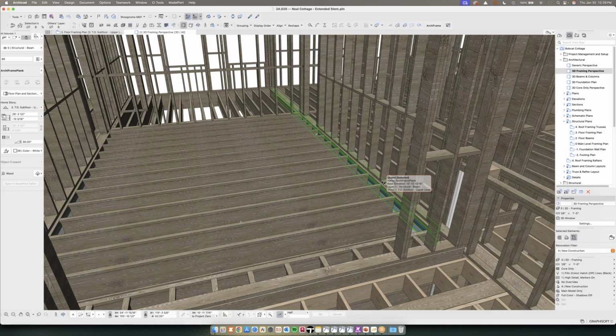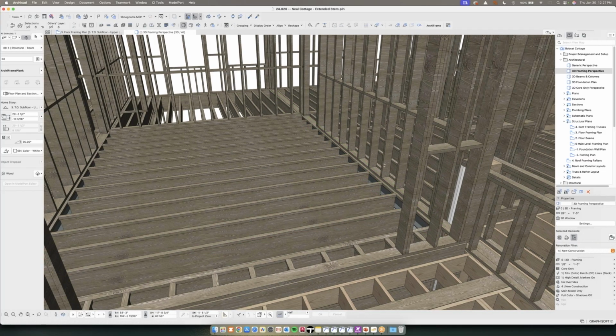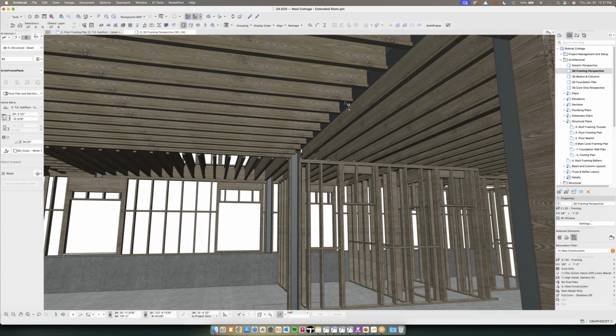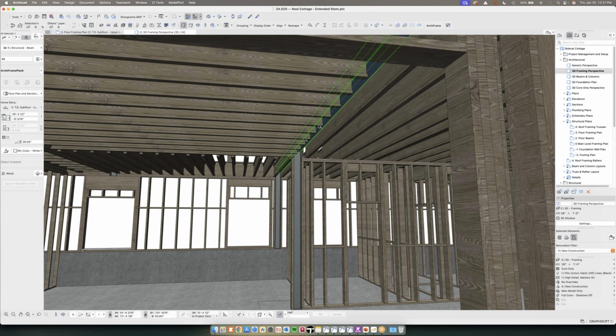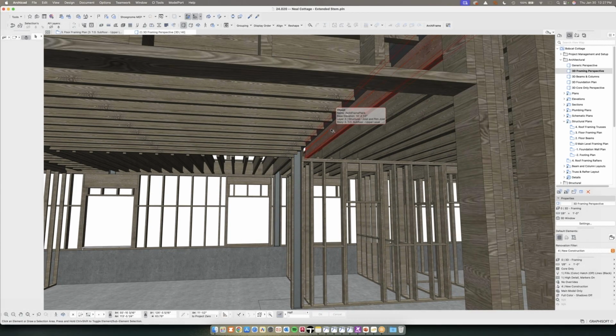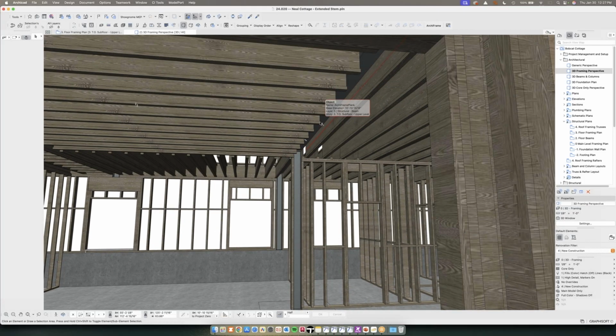So we went with a steel beam header in here, and we can see here how there's a big drop from the underside of the steel beam to the 16-inch I-joist floor joists. And that's primarily so that we can get plumbing and HVAC and mechanical structures underneath without needing to cut joists or to drop bulkheads in this building. So again, to be able to share this level of information with the client is hugely powerful.